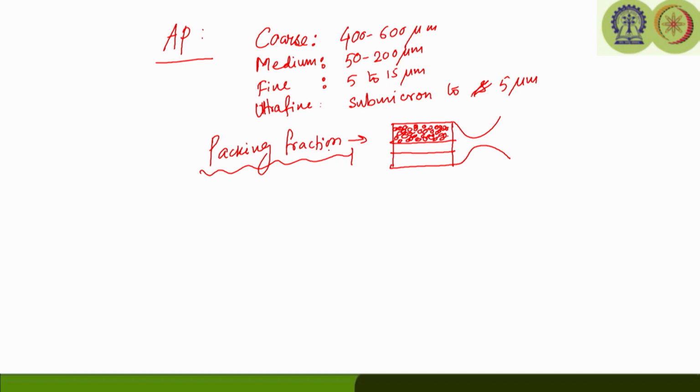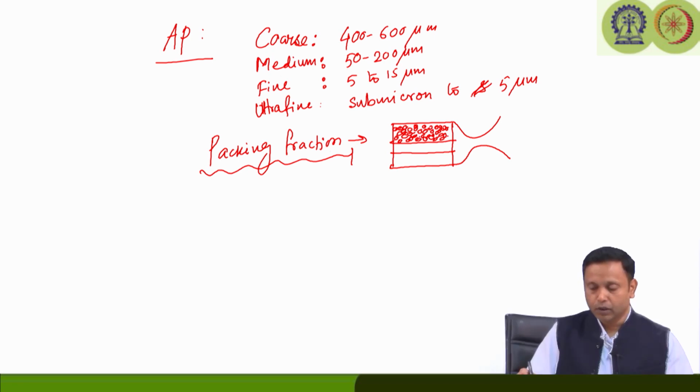Solid particles here means aluminum or boron as fuel, and ammonium perchlorate as the oxidizer. Now, there are difficulties when we put too much solid fraction within the propellant grain, because if you look at the uncured propellant, we put too much ammonium perchlorate as solid crystal oxidizer, and we put aluminum particles there.